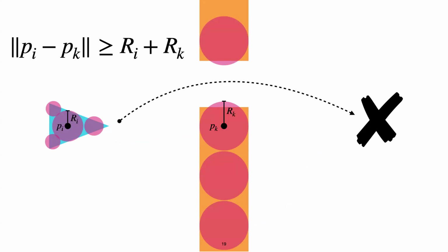And you'd think that if we can solve all these problems that modern robotics people can solve, it must be very easy to solve this one. Exactly. And the way you actually solve it is way hackier than you'd think. You basically decompose the environment into a bunch of spheres, and you decompose your robot itself into a bunch of spheres. And I write down all these constraints that make sure none of these spheres touch.